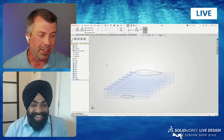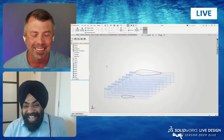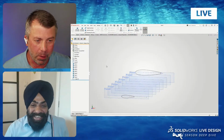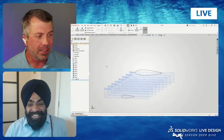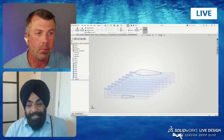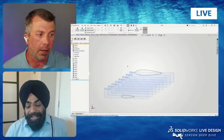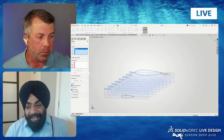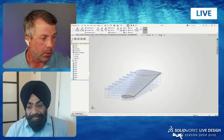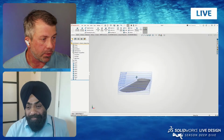Yeah, okay. I'm a surfacing guy, so my instinct is always, can I surface it first? Which is probably the wrong way to approach things. But yeah, let's do solid. Let's take a look at the solid. So we're going to do a lofted boss. We'll grab this wing. We'll grab this wing, and that looks pretty dang good. Click the OK, and we have our lofted wing.